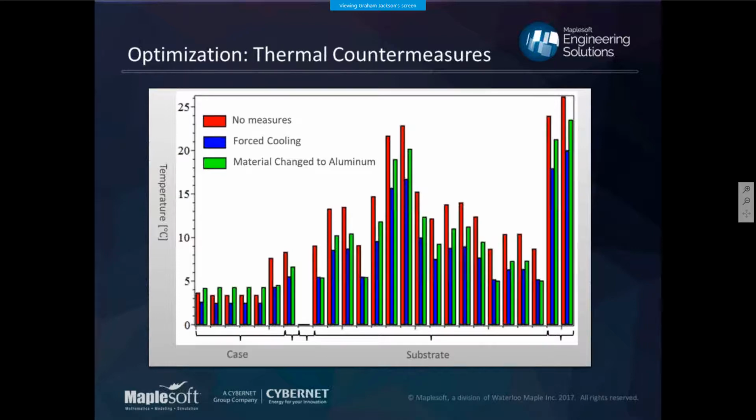And what we're seeing here are the results. They show that we succeeded in suppressing the temperature of the heat-generating component to 50 degrees or lower by changing the material. So that worked, that was good. On the other hand, the forced air cooling is also effective. But then just practically, we think that forced air cooling potentially introduces a larger host of other design implications.